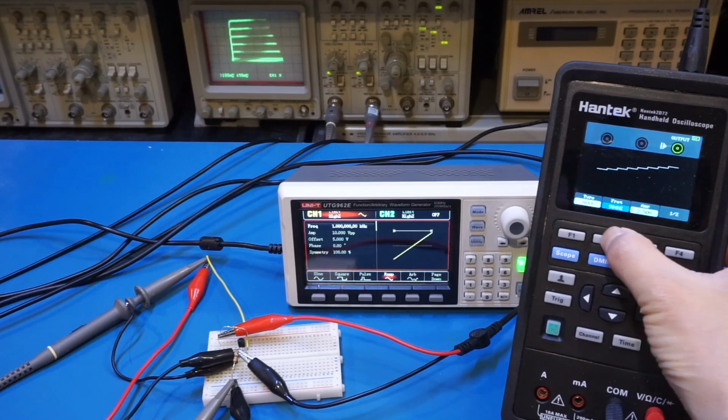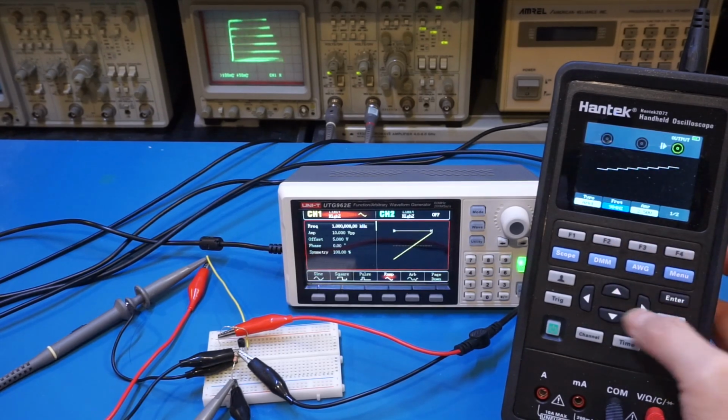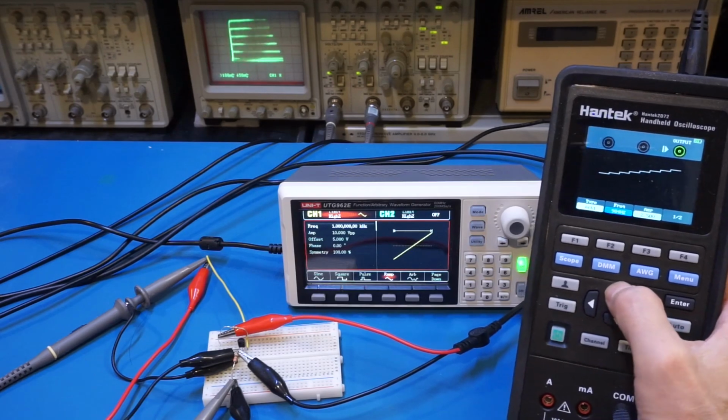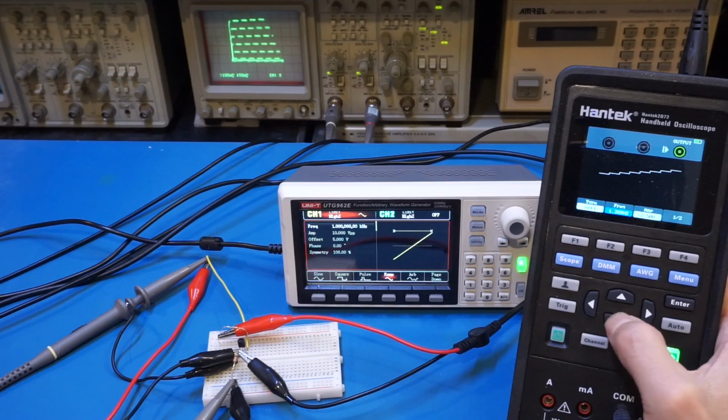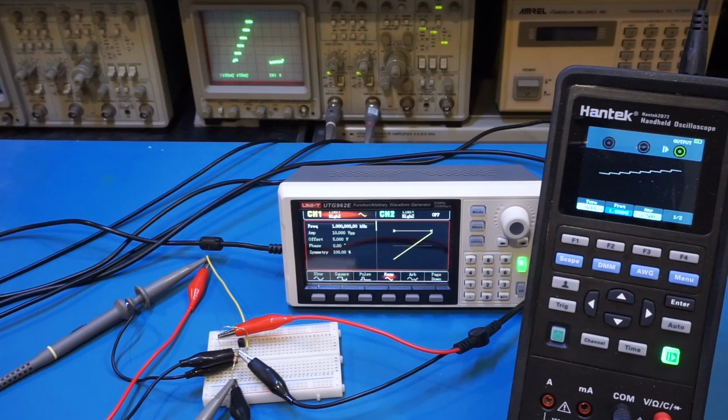So let me, for instance, increase the frequency of this staircase signal, and let's actually go down. If we are getting closer to that 1 kilohertz, you will see that we will be generating a beat, which makes it very hard to see. And at exactly 1 kilohertz, the generated image is actually not quite legible here.